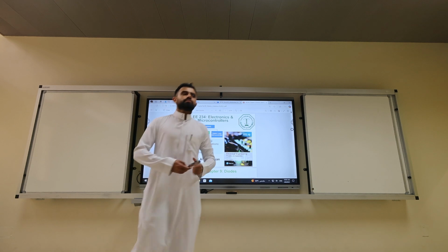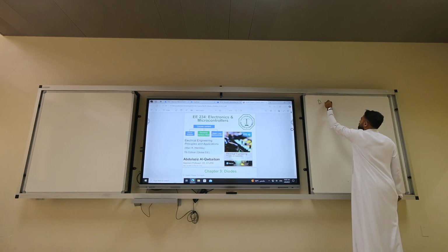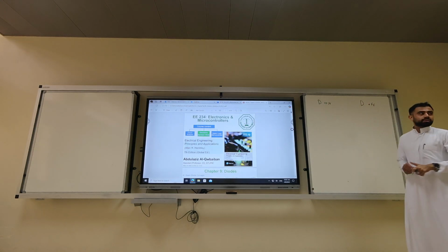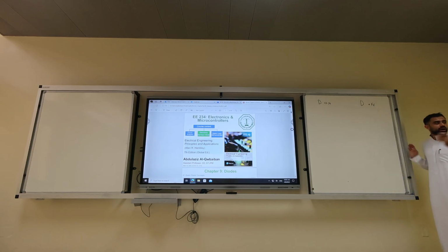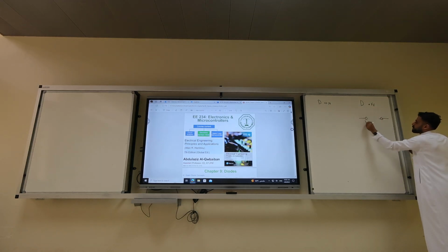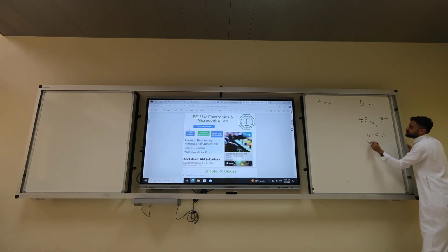So last time, what did we say? We either have diode on or diode off, right? Jihad, what did we say when the diode is off? How do we represent it in the circuit? Open circuit. And we say plus minus VD. What is I diode? 0. What is V of the diode? Has to be negative.